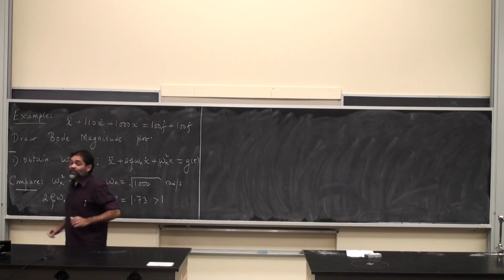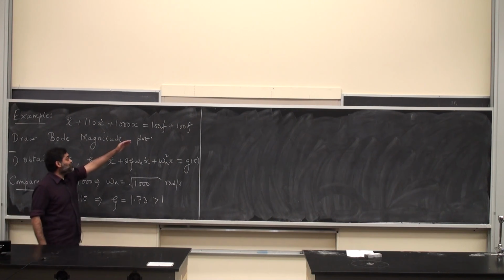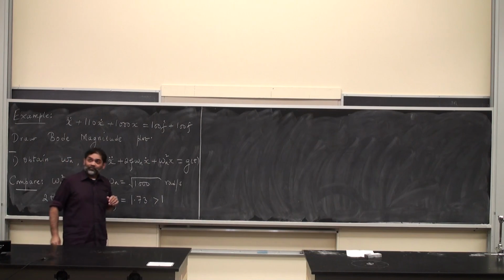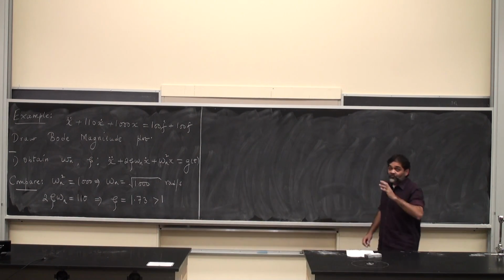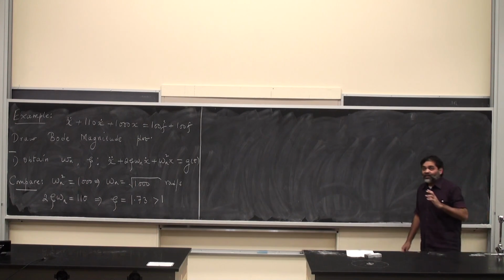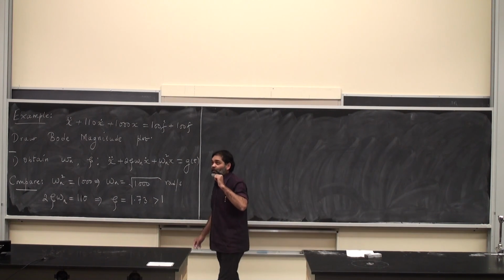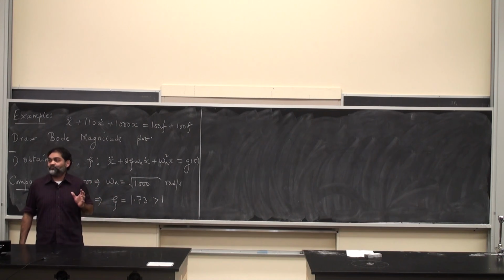And then what we do next is the following. You see in this particular problem we have numerator dynamics, right? You have certain derivative terms existing on the right hand side. Those are called the numerator dynamics. What we will say is this. If there were no numerator dynamics, and if the value of zeta was 1.73, would I see any physical peaks in the magnitude plot?